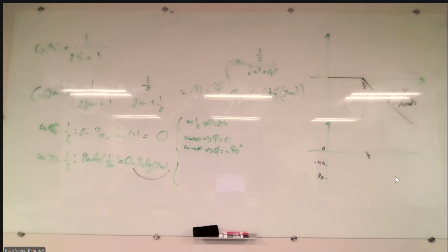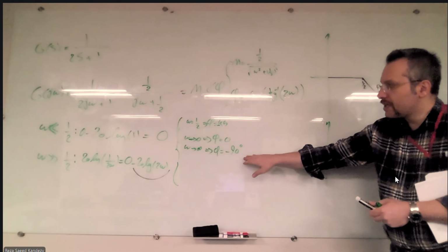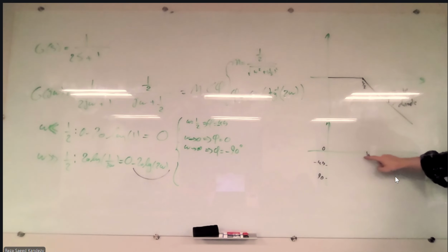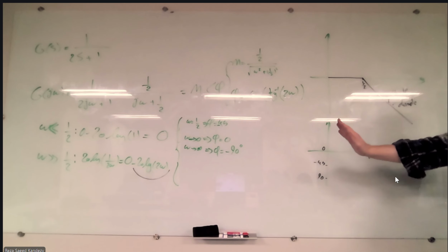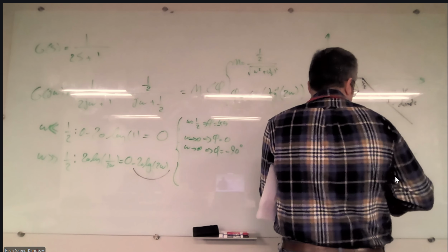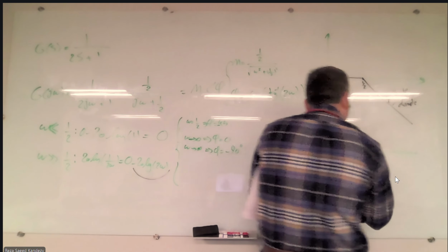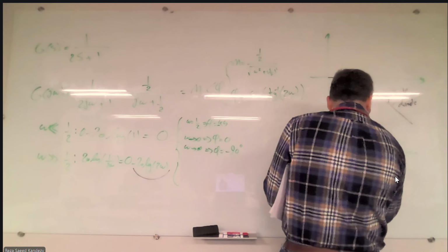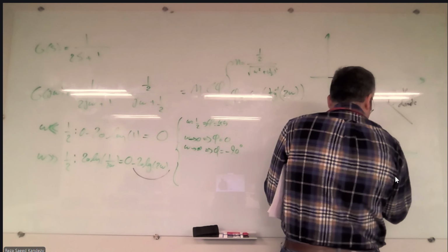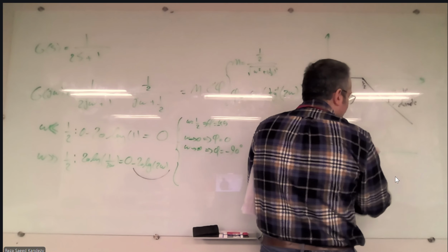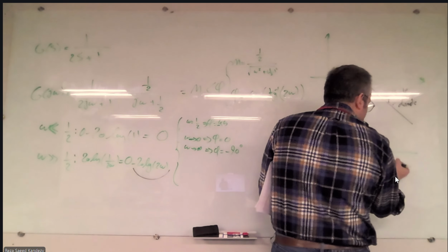Now, we said when we wanted to show this phase, what we need to do in the graph is, for this 1 over 2, we need to consider another 2 points. One is a decade before 1 over 2. This is basically 0.5, so we are going to have 0.05 here. Let me actually, this is 1 over 2, and this is going to be 1 decade before that, and then 1 decade after that, which is 5.